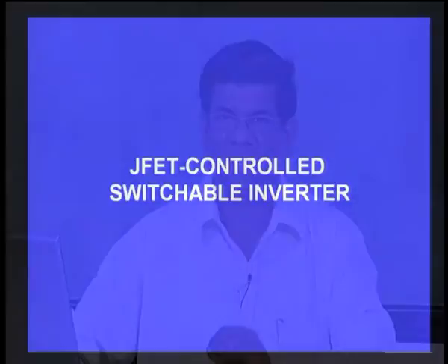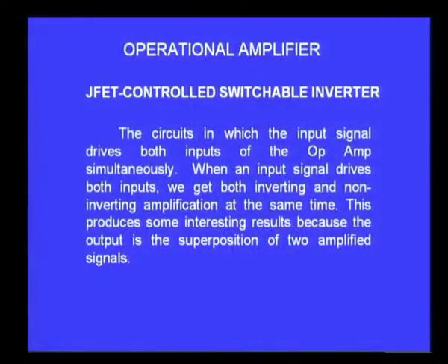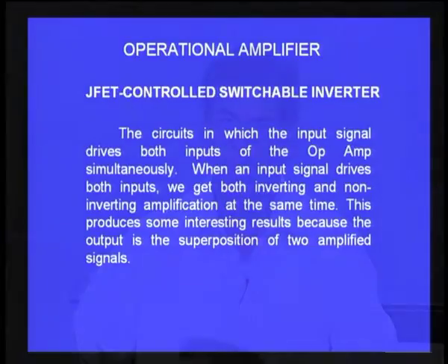The input signal drives again both the inputs of the op amp simultaneously, the inverting as well as the non-inverting, and therefore, we will get an amplification corresponding to the inverting amplifier as well as a non-inverting amplifier, and the effective output will be the superposition of these two. So, we will get a very interesting result here also.